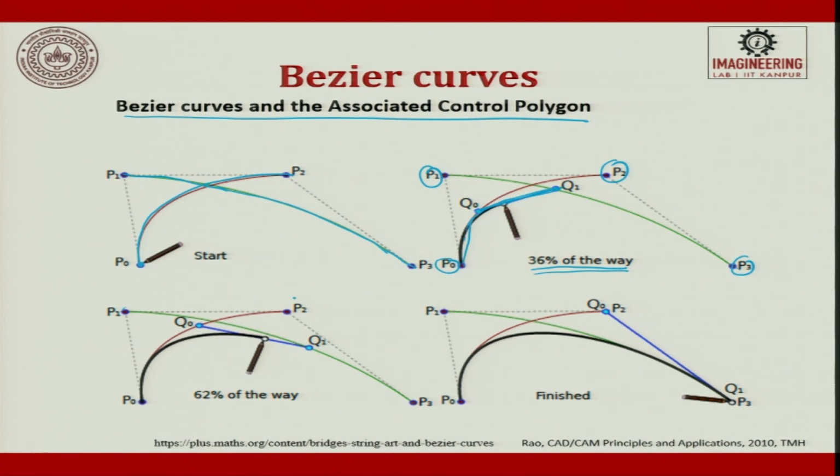P1 and P2 are control points, Q0 and Q1 are during the motion which is trying to establish, and then you will try to convert it into a straight line, and that tries to connect between these two curves. Now, what is clear? If I try to move P1 or P2 or both, you can see the complete curve gets dictated. That means by changing one point, the complete curve profile changes. That is the understanding you should have in this Bezier curve.